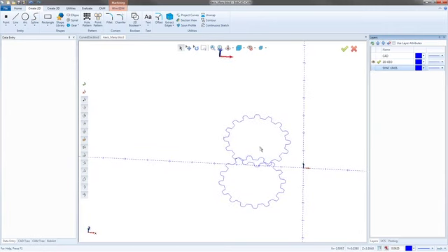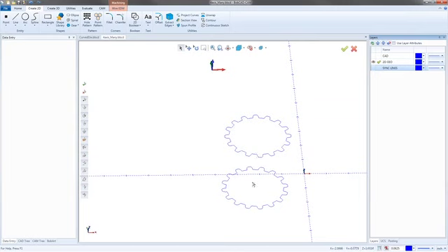And so the only other thing I want to check on is just make sure these two parts are good. Make sure they're clean. So I'm going to cancel out, grab my select tool, and then just hold shift on my keyboard and click on these shapes. What I'm looking for here is that they light up 100% around. If there was a stop, if it went around and then stopped where the blue and the red, my part's blue, so that's what I get. Where the red and the blue meet, that's where you want to zoom in and start looking.